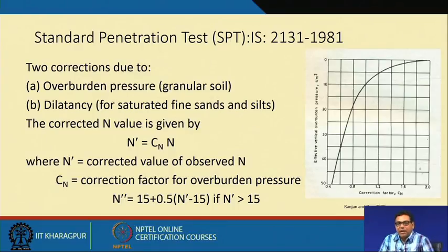Now, as I mentioned, our pore water pressure is negative. So total stress minus pore water pressure becomes plus: the total stress plus u, into tan phi.